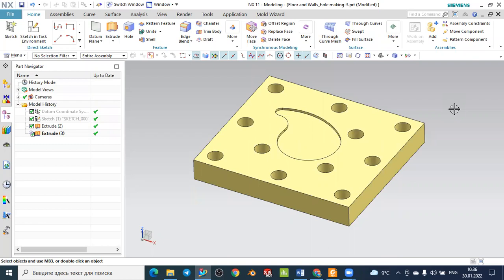Today we will see the CAM operation, computer-aided manufacturing, and how to obtain pocket milling with the floor and wall IPW method. We will also see how to create the drill cycle and create the holes, and we will learn how to obtain hole recognition.